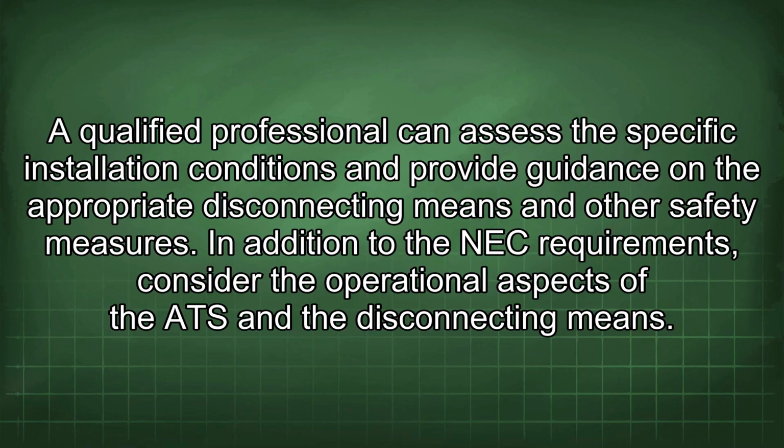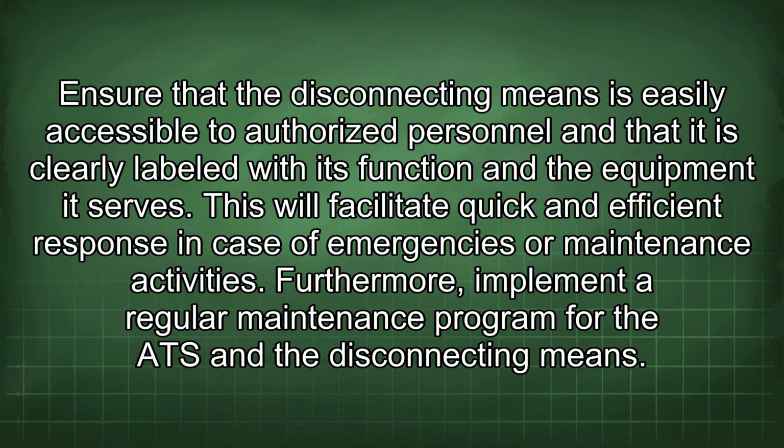In addition to the NEC requirements, consider the operational aspects of the ATS and the disconnecting means. Ensure that the disconnecting means is easily accessible to authorized personnel and that it is clearly labeled with its function and the equipment it serves. This will facilitate quick and efficient response in case of emergencies or maintenance activities. Furthermore, implement a regular maintenance program for the ATS and the disconnecting means.